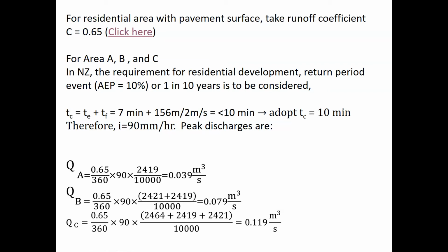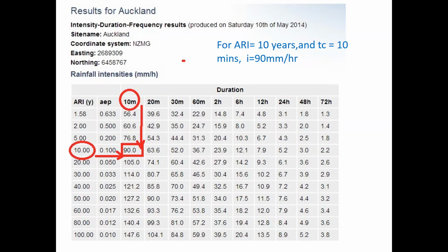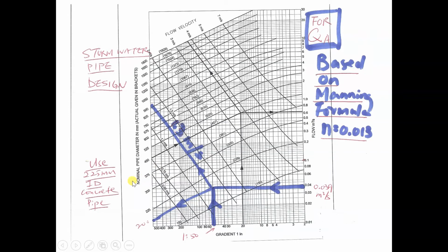Okay, so for this stormwater pipe, we could calculate it, but because the pipe is round, it's a bit hard to solve it by equations. Solving by equation is usually for regular shapes. If it's rectangular, then it's easier to find the area of the drain. If it's a round one, it's a bit hard because the water is at different levels. So that one you use a chart method, which is easier.